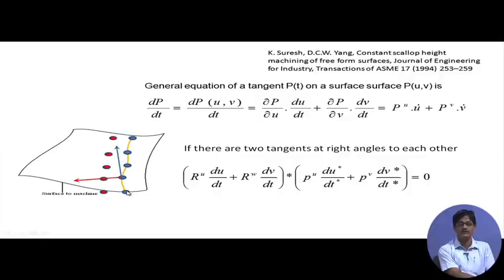That part is done. Then we are trying to find out the positions of the cutter path, cutter contact points on the potential cutter path by the side of it, which has not been found out up till now. We are trying to calculate the positions on this particular cutter path, which will give us acceptable side step.